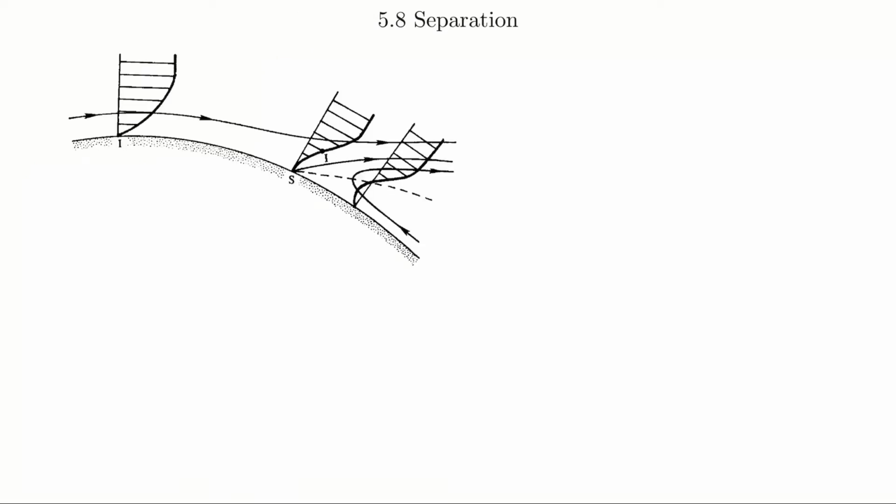So we've zoomed in here on our decelerating region in this figure here. And we just saw in the last section that the boundary layer in the decelerating stream has a point of inflection and it grows rapidly, okay? So this point of inflection implies that the fluid is slowing down in the region close to the wall. And we can see that because we have an adverse pressure gradient, right? That's pushing this way, okay? So we see in this velocity profile, we're slowest near the wall.